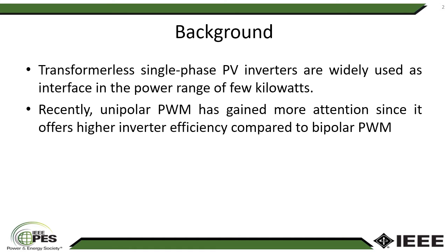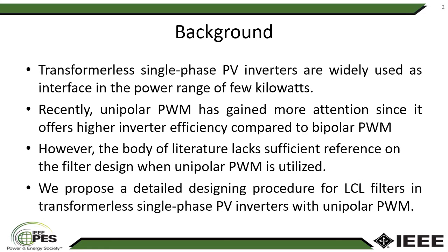On the other hand, an LCL filter is mandatory to reduce the harmonic content of the grid current, and there is not enough information in the literature to design an LCL filter when unipolar PWM is utilized in single-phase transformerless PV inverters. So in this paper, we propose a detailed design procedure for LCL filters in these types of converters.